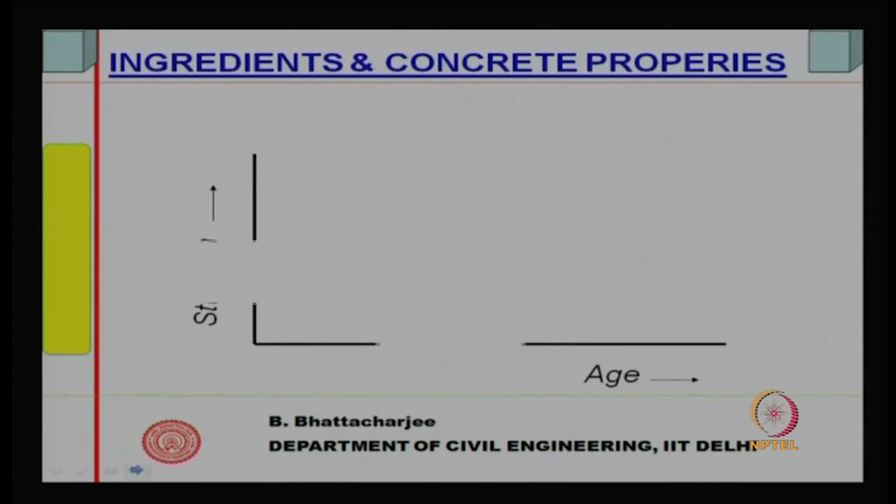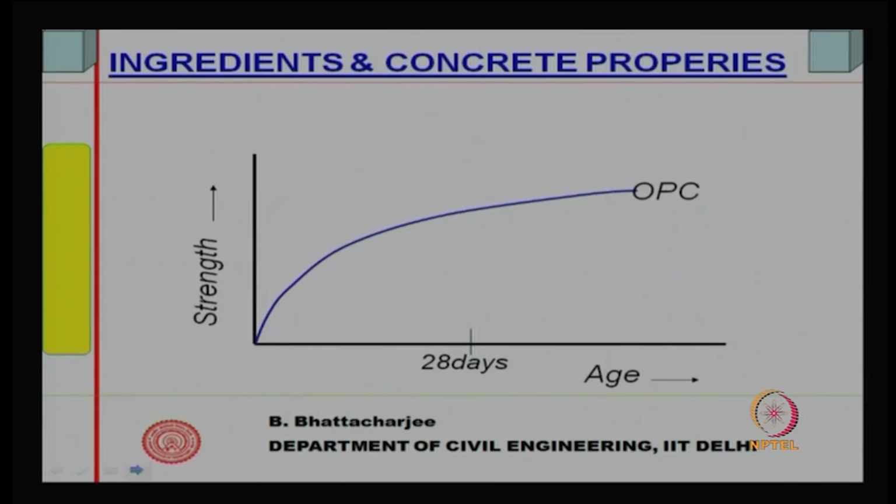The strength part is important. If you see strength for concrete without fly ash, it is something like this, and if I have fly ash concrete, let us say I design for identical 28 days strength, the early strength will be less, but the long term strength is much higher.